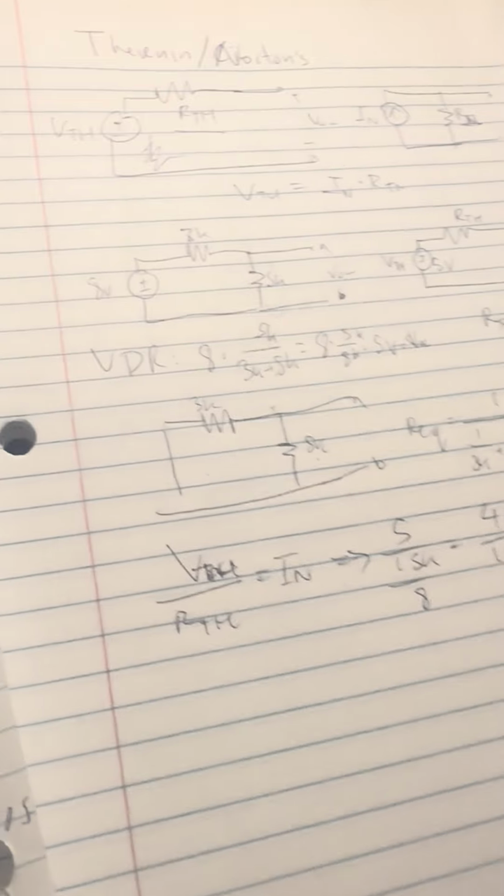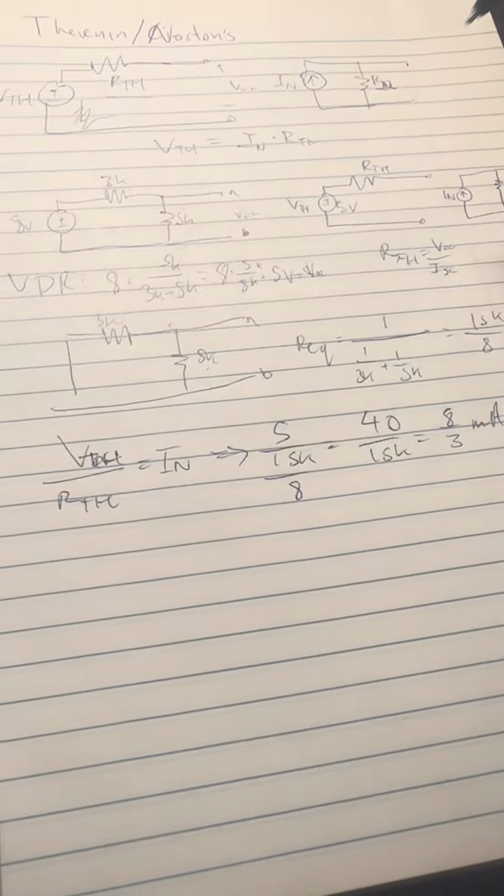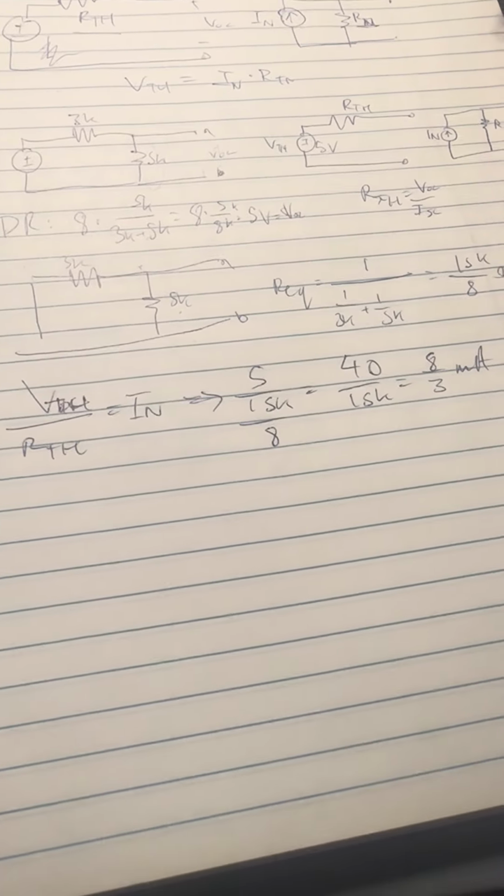This is not a fun circuit. However, this is how that works. But the problem is, you can only turn off independent sources. You can't turn off dependent sources. So for that you need to use the test signal method.